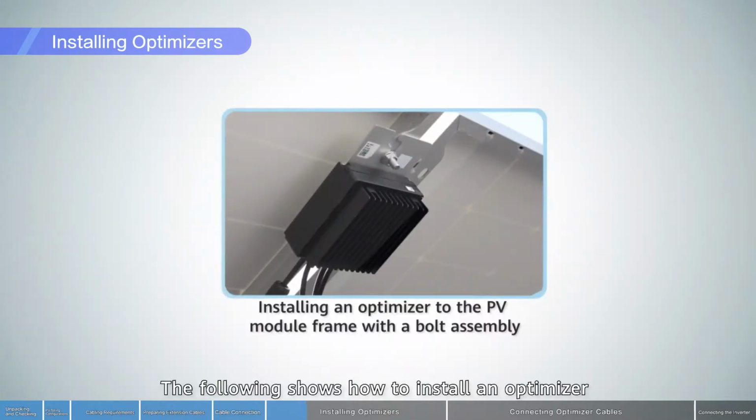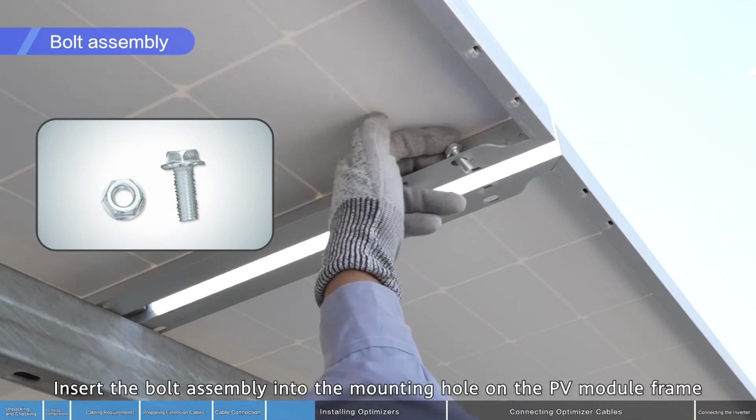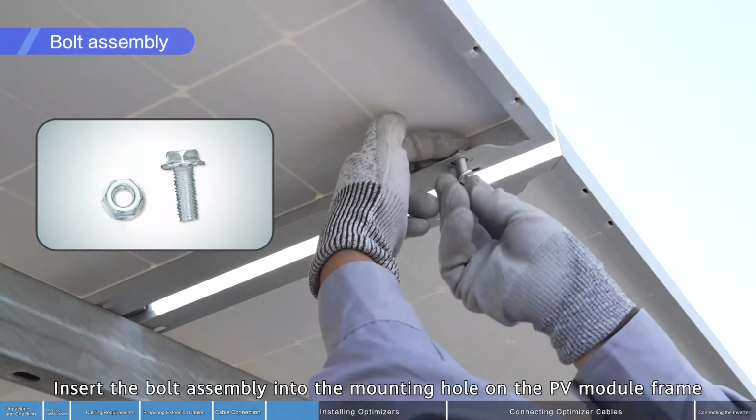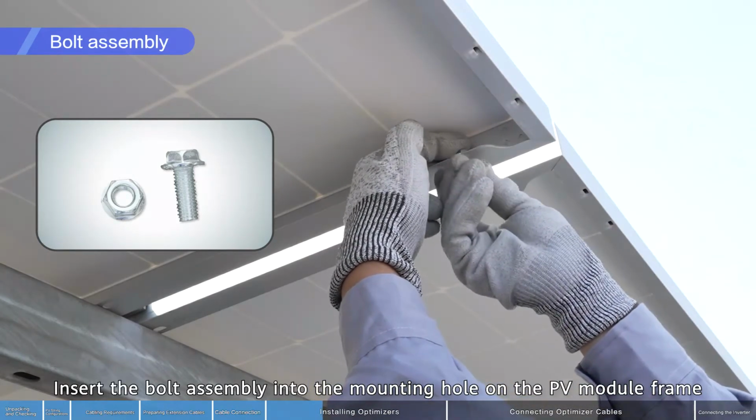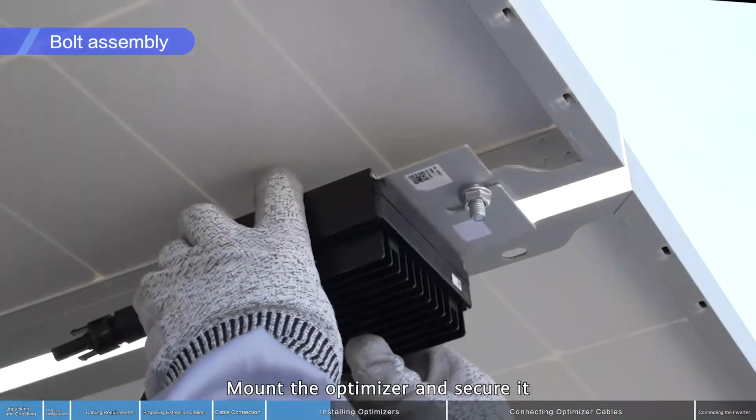The following shows how to install an optimizer to the PV module frame with a bolt assembly. Insert the bolt assembly into the mounting hole on the PV module frame. Mount the optimizer and secure it.